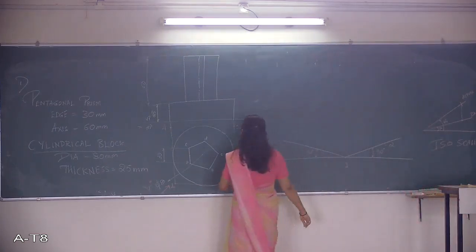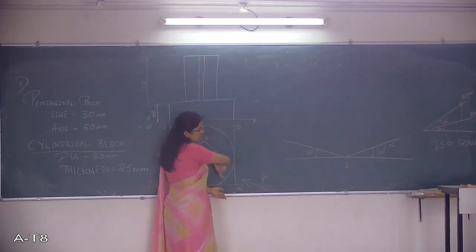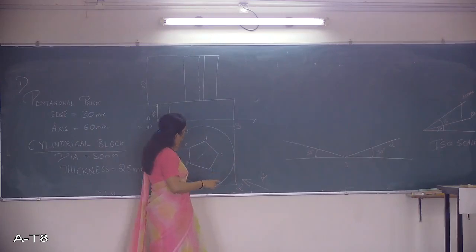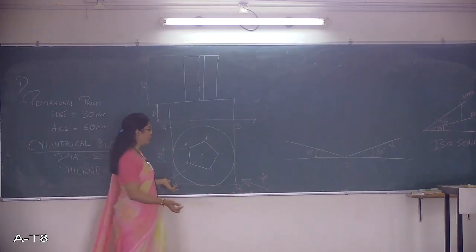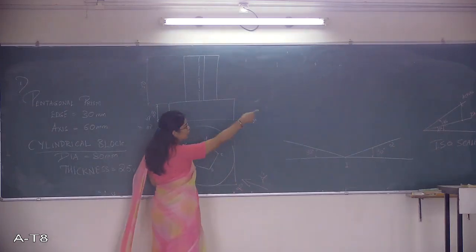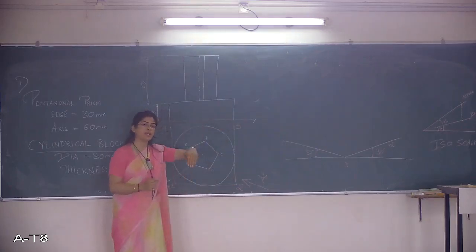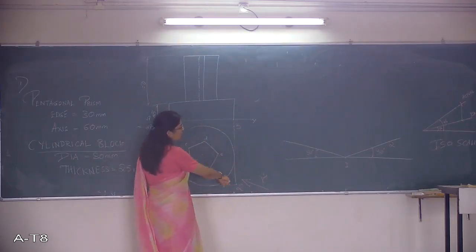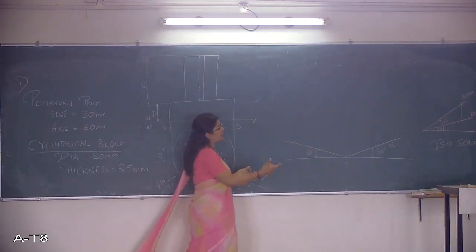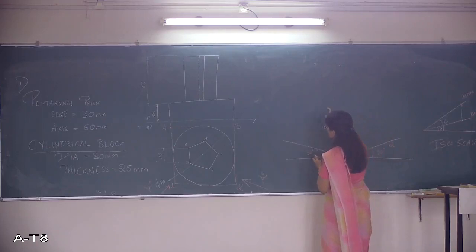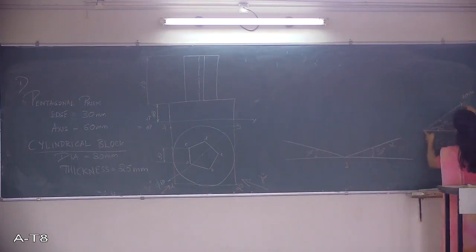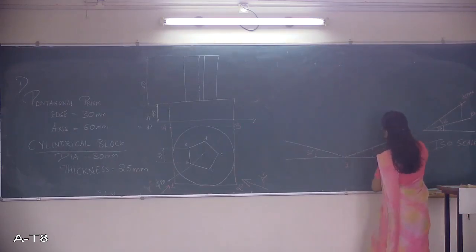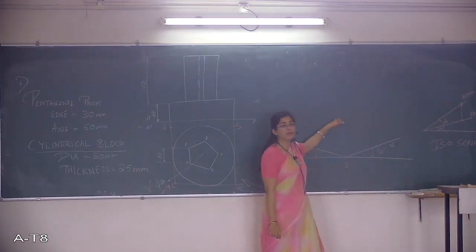Next, let me go for 2 to 3. As it is a circle, basically, the box that we get around is a square. It will have all the sides equal. So if you want, you can keep referring to each side again and again, go to the actual scale, get the iso scale value, or you know that it is going to be the same throughout because it's a square. You can take the same compass marking and go on marking such that you get 1, 2, 3 and 4. So by taking 2 and 3, again you go here. If you want, mark it here, you'll get the same iso scale reading. From 2, you mark an arc such that you can mark here 3.